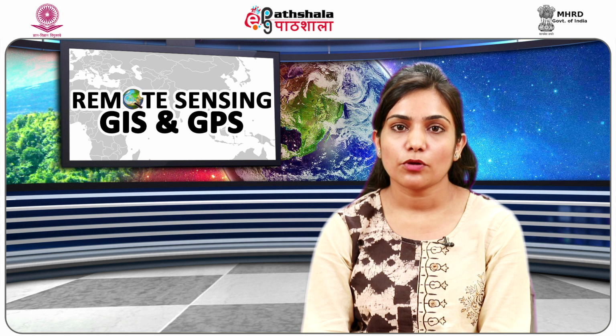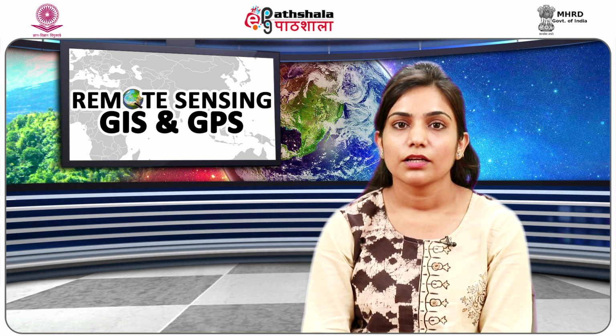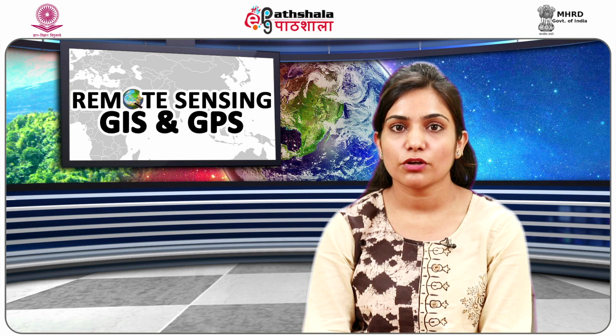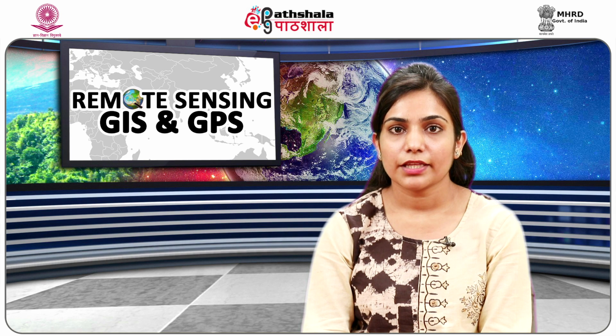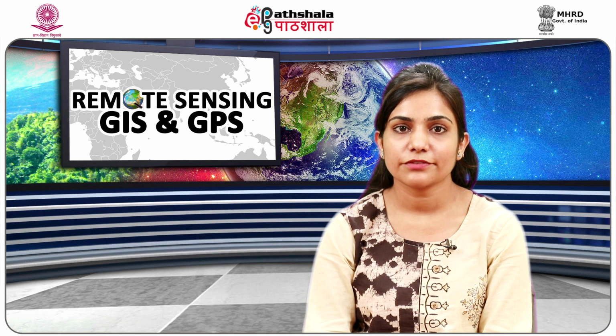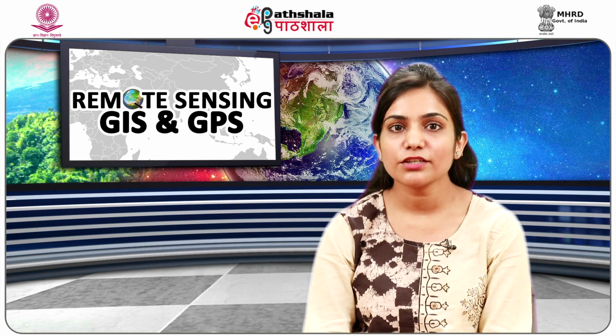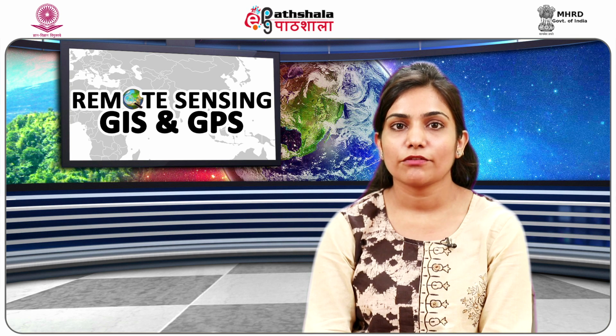Using a computer called a stereoplotter, the stereo pair can be viewed as a single image with the appearance of depth and relief. Ground control points are established based on ground surveys or aerial triangulation and are viewed in the stereoplotter in conjunction with the stereo pair. In this setting, the image coordinates of an XYZ point in the stereo pair can be determined, randomly selected and digitized. These points in conjunction with the control points comprise the data points for the DTM. The accuracy of the final digital orthophoto will depend in large part on the point density of the DTM.